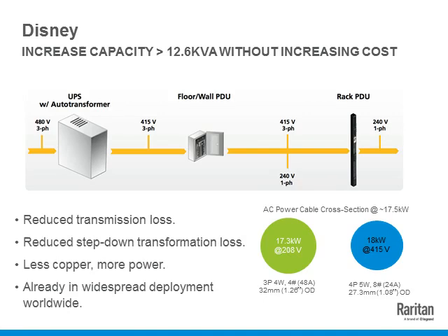So here is an overview of how that architecture looks. You have a traditional 480 volts three-phase coming in at the utility level. Typically, this would have been stepped down to 208 volts three-phase in the U.S. The new design on 415 volts was to step it down just enough to bring it to 415 volts three-phase, making it a 240 volts single-phase line to neutral. So that makes it perfectly safe for the servers because they can run all the way up to 240 volts at a single phase.